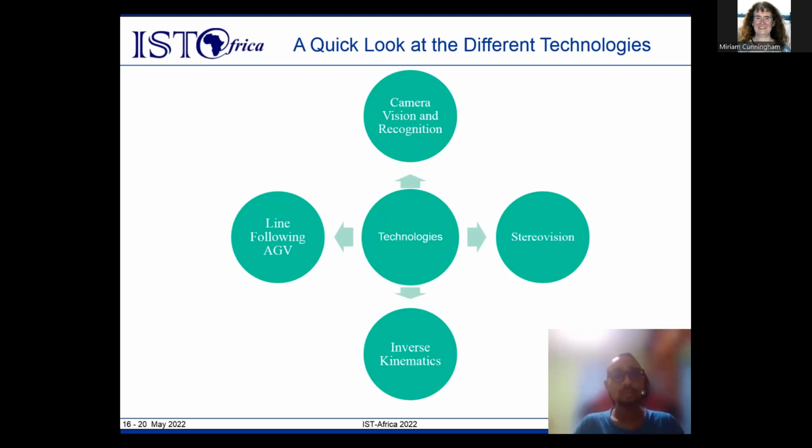We also have the stereo vision technology. What is a stereo vision technology? It is basically a system of 2 cameras where we can visualize a 2D scene to a 3D one, just like our eyes work. Therefore, we can extract the distance or real-world coordinates of the tomatoes, and these coordinates can be transferred to joint space to rotate the arm to pluck the tomatoes via the technology known as inverse kinematics.